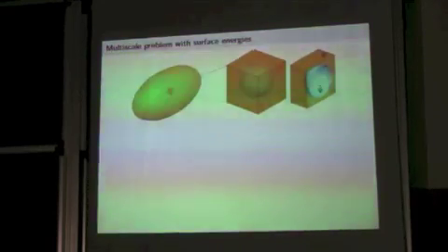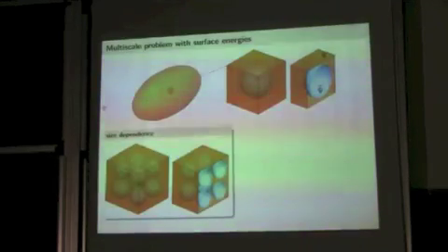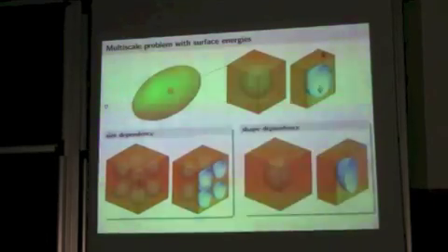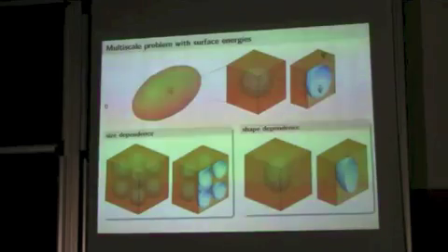We have also heard about heterogeneous materials and homogenization. This is another thought about that. If you have a material with a heterogeneous microstructure like this one, say a nanoporous material, what we do is add additional surface energy on the surface of these pores inside. This is something different from what people do in classical homogenization, where you don't have this. Adding this gives you two very interesting effects. First, it gives you size dependence, which you generally want to have, and it gives you an additional shape dependence. It's not just the anisotropy effect and things like that. It's also the change of the area of this.